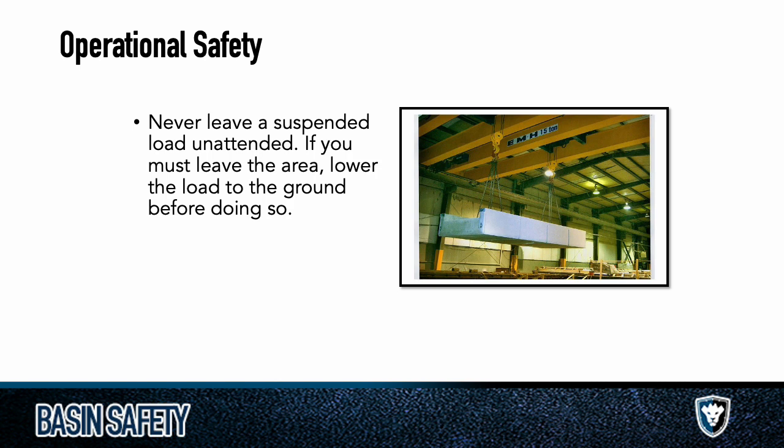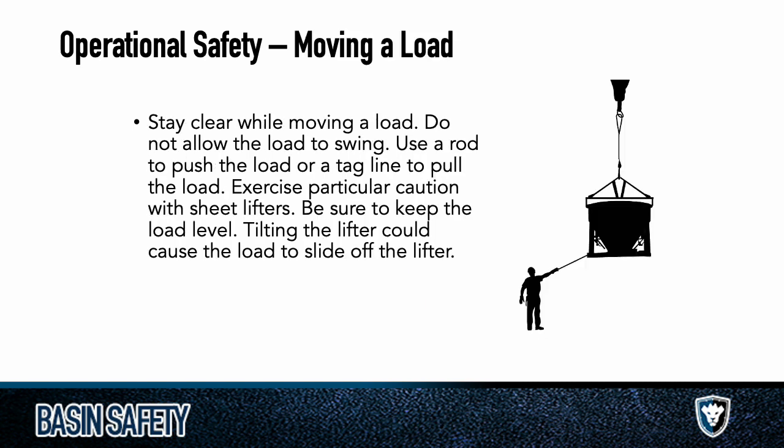Never leave a suspended load unattended. We don't want to lift it and be like, lunchtime, leave it hanging in the air and go. That's a no-no. We want to make sure that while the load's engaged, there's someone always in the equipment and that they always have a signal person available for that crane. So when moving the load, I already kind of talked about this. We want to make sure that we stay clear.